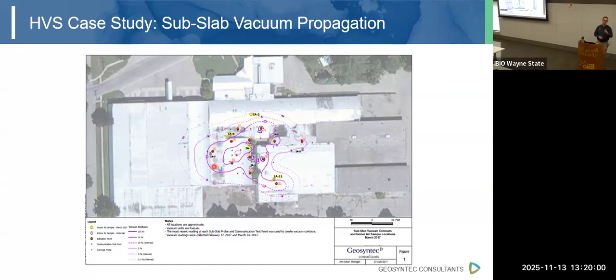I will say too, there are buildings where the source is so significant that we actually need to treat the vapor before it comes out of the stack. So we have carbon drums where the VOCs are sorbing onto the carbon instead of going out into the outdoor air. And there are different permit exemptions for these mitigation systems on the air side, so we don't have to get an air permit to address this sort of local health concern.